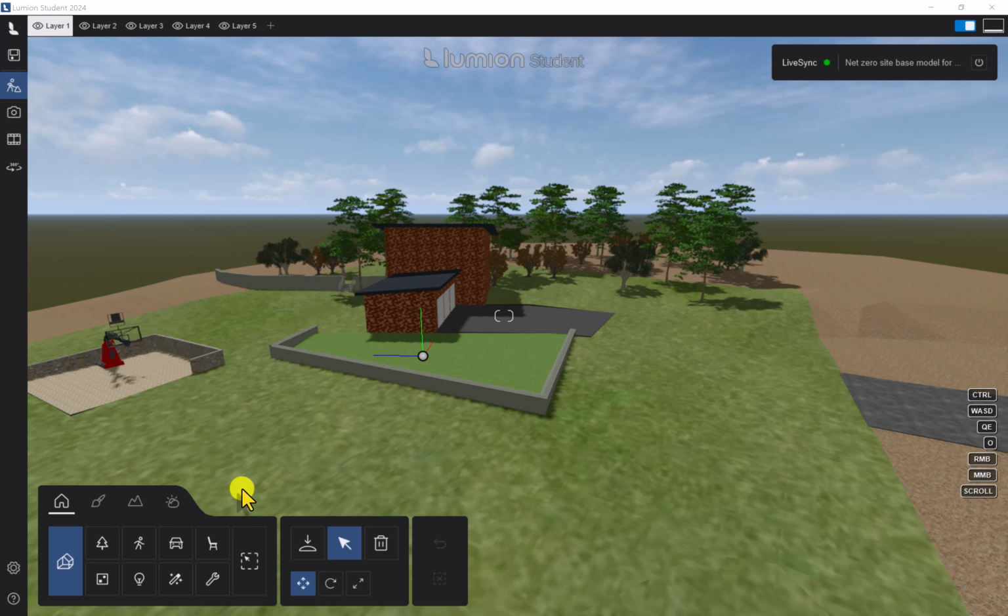Now, also, things that are largely flat-ish with square or linear edges, again something like a lawn, but also a patio, are items that you'll want to draw in Revit using the features mentioned before. Things like floors are probably the best option.